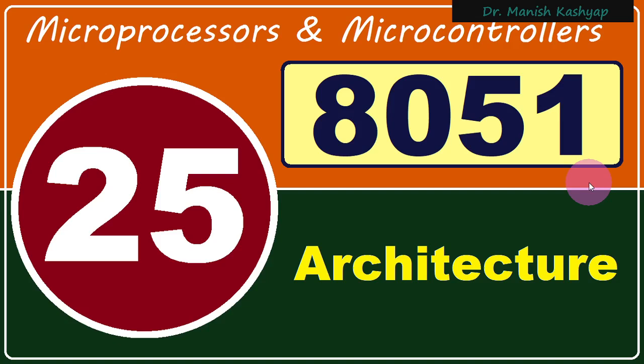The only point of difference will be in the execution speed, because when you fabricate all the components on the same chip, the peripheral and the brain part communicate at a faster speed than when you connect a microprocessor to its peripherals through wired external connections. Those external connections are definitely slower. So 8051 will be faster as compared to 8085 and 8086.